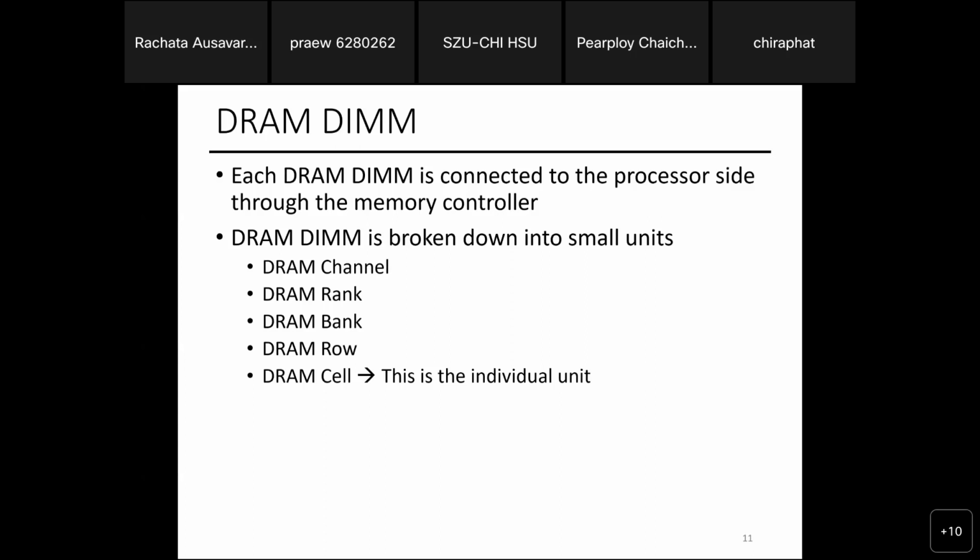When I say the word clock domain, it's basically this. You can have one global clock signal, but you can use multiple domains by using different logic to slow down the clock, essentially. All right. DIMM stands for dual inline memory module. We'll go into each of these subunits of DRAM in a bit. I want to go through some figures first, so you see that in action.